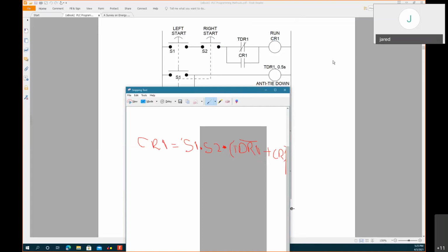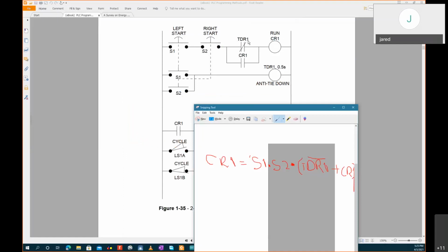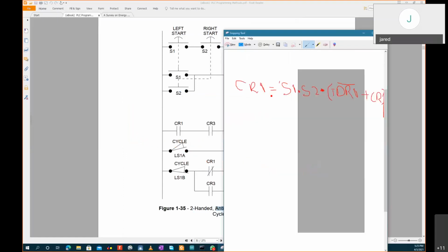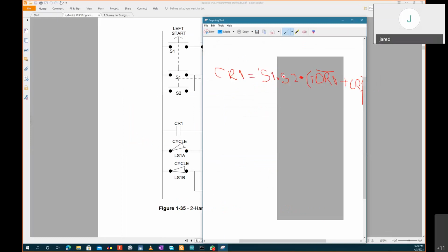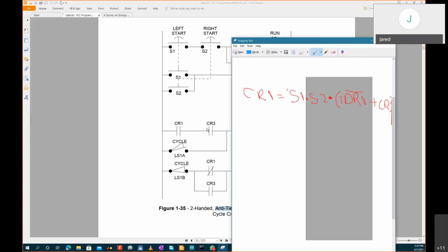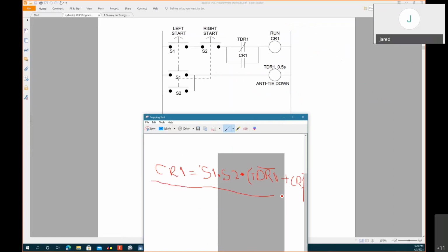And now you can go to the second logic and write the same thing, because this will be a starting point if you're given a statement or a function and told to develop a circuit for it. You'll first write this representation, even before going to the logic diagram, so that you can work it out in your head and understand what you want to achieve. Because to get to ladder programming, you must be able to write this statement correctly. This is what you're going to put in the PLC, and if you write it wrongly, the PLC will give you whatever you actually produced. So they always say garbage in, garbage out.